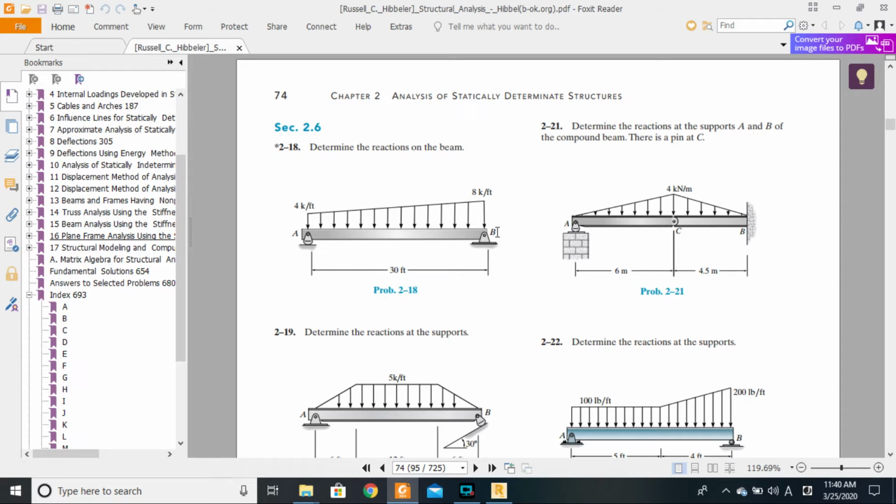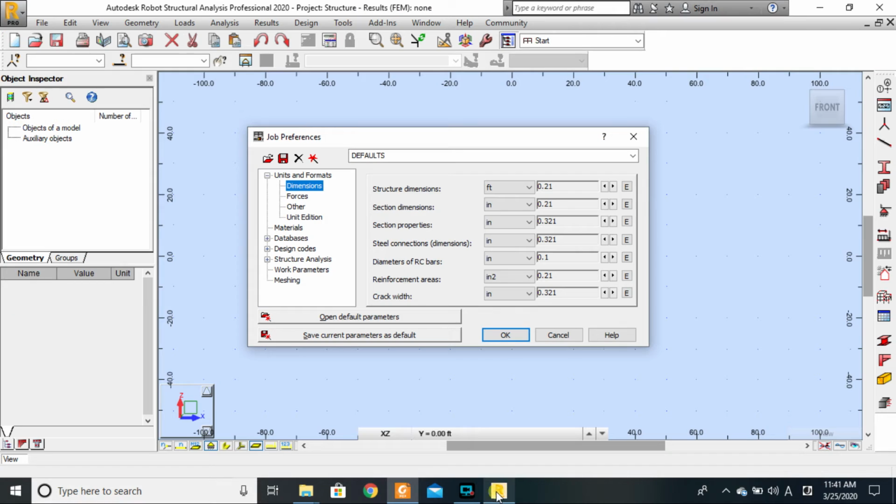It will have a particular thickness for the web. The web is a section dimension. Okay, it has a particular overall height, a particular overall breadth. Those are section dimensions because they are dimensions of the sections of the elements. Those dimensions are generally relatively small compared to structural dimensions, so we express them in inches so that we can manipulate them easily. But I digress. The structural dimensions here would be enough for this particular example.